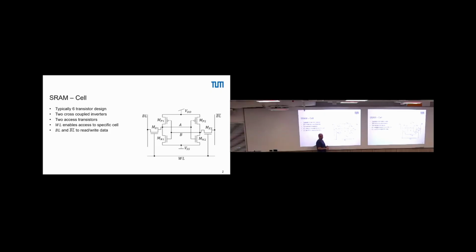A sense amplifier is built to sense the difference between two wires, these two, and to amplify it to VDD or ground. That's an analog circuit. It looks pretty much like an SRAM cell, just with different sizing. Good. So we need one sense amplifier on top, another couple of transistors.